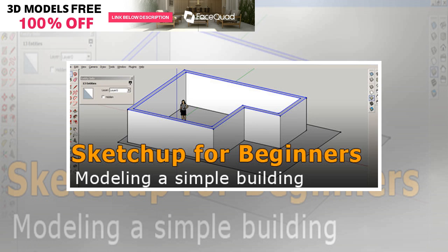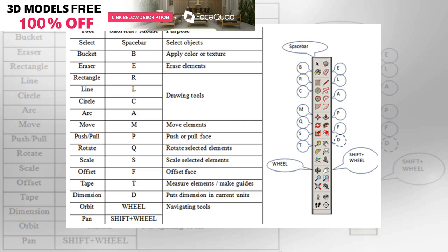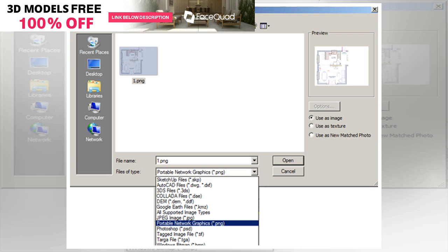Let's make this floor plan properly scaled so that we can outline structures, furniture, whatever is needed. With the Tape Measure tool T, press Ctrl and measure the current value of any known dimension, no matter interior or exterior. Try to use the largest dimension to minimize error. We may use 6330 mm, the width of the living room. You will see the measured dimension in the bottom left corner in the white text box. The current dimension is usually wrong.